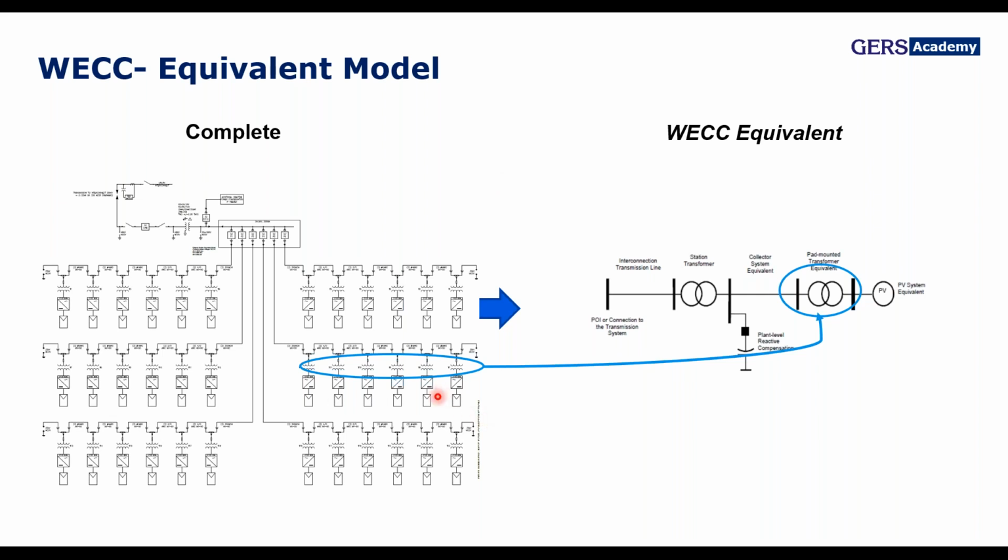So as mentioned before, you have some methodologies to create an equivalent transformer. But normally that transformer is similar in all units, and the values are around 6 to 8% based on the MVA of the transformer.